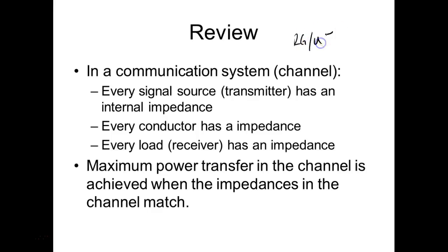What they decided to use in cable TV is RG59. Are those two compatible? What's the difference between them, besides size? One of them is 75 ohm, one of them is 50 ohms. RG58 is 50 ohms. This is what we used to use on networking all the time. RG59 is 75 ohms.